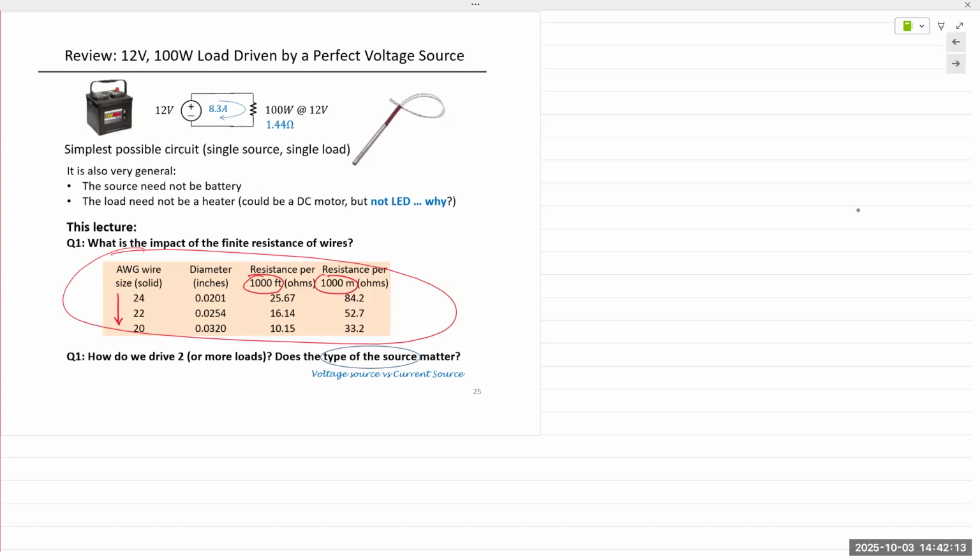So if the wire gets hot, what's going to happen? It's going to melt the insulation if it's not designed to handle it. It melts the insulation, then there are going to be bare conductors touching each other, creating a short circuit, and it's going to blow out your circuit. It may even cause a fire to start. For that reason, manufacturers will not spend a whole lot of money making those power hungry cables. They make the cable very short so that the power does not have to transfer over long distances.